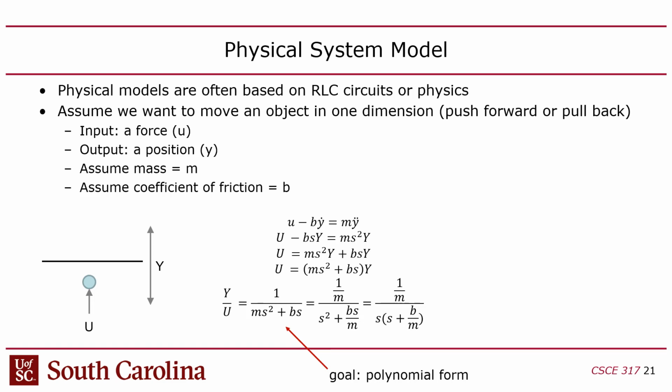This is now the control system part of this, where you conceptualize this as the transfer function. So you can essentially convert this to the Laplace domain. The y dot is sY, and the y double dot is s squared Y. And you've got to use the capital letters though. You've got to go capital, because that's important. You've got to go capitals on these when you go Laplace.